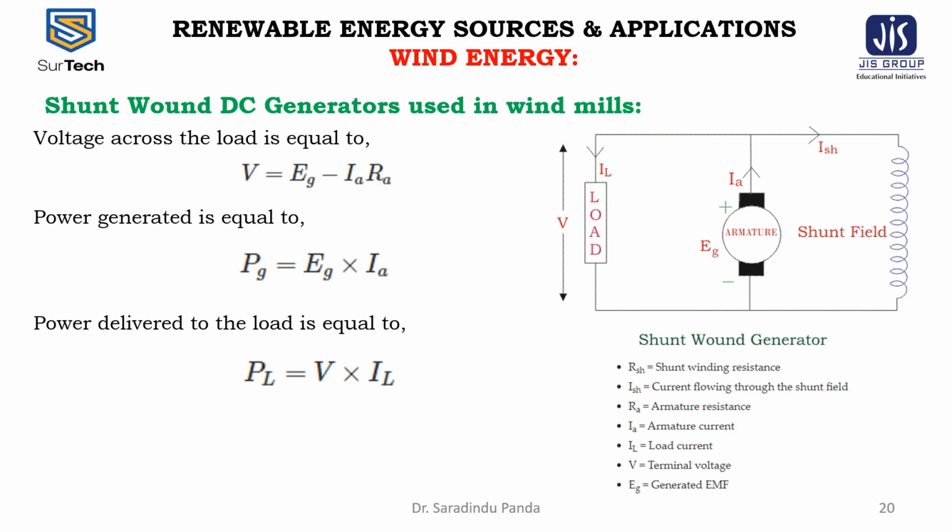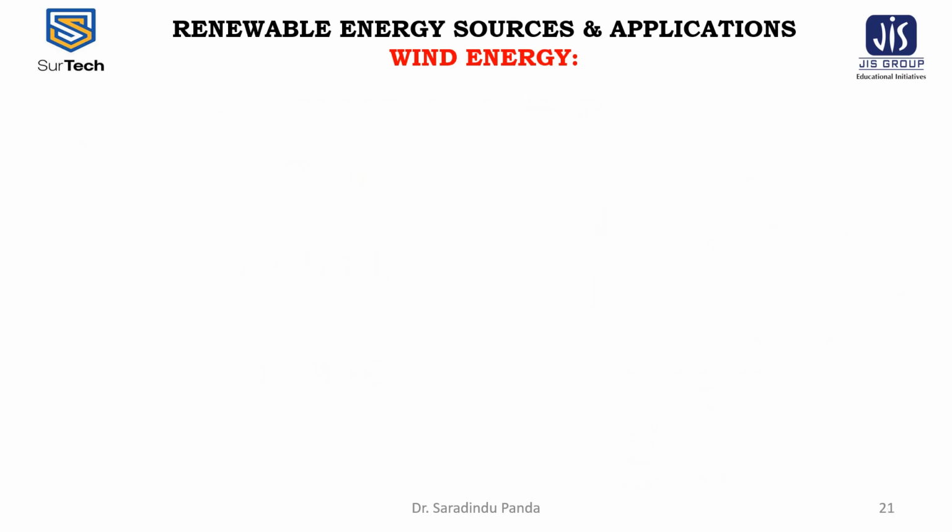However, a compound connected DC generator has a combination of both the shunt and the series windings incorporated into a single generator, and which can be so connected as to produce either a short shunt compound DC generator or a long shunt compound DC generator. This type of self-excited DC generator design allows for the advantage of each type to be included into one single DC machine.